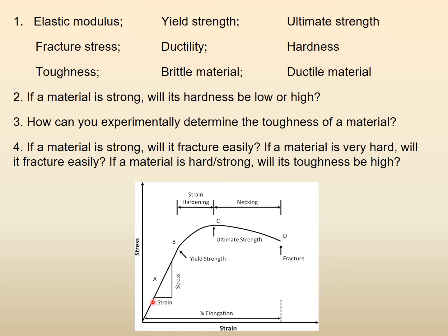Okay. Now the same curve, if you go now, this is the second material. So you go here, at this point it fractures if it was a brittle material. If it is a ductile material, it fractures here. So strength wise, they are high strength. Which fractures more easily, right? So you see, your answer is find its toughness. To answer this, find its toughness.